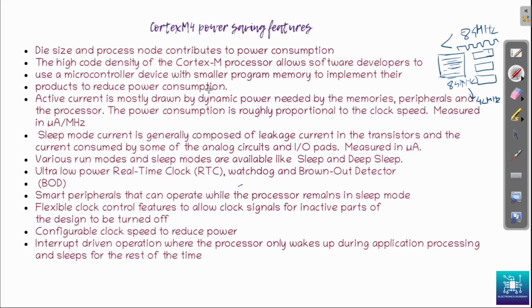And we learned that it is not even wise to have a higher amount of memory than you actually need, because that also adds to the power consumption. The active current is roughly proportional to the clock speed, and it is measured in microamperes per megahertz.